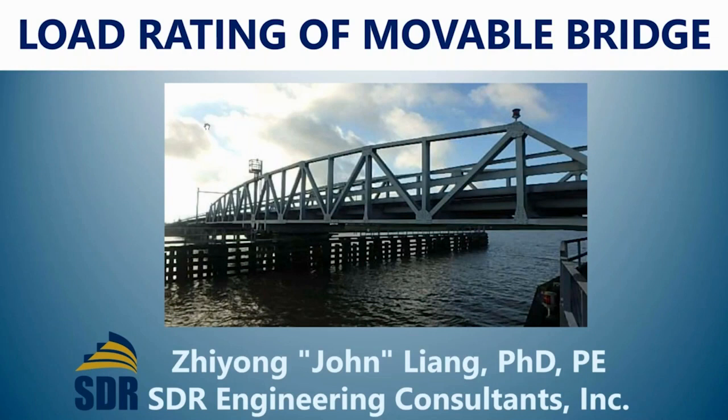So it's very important for us to load rate those bridges because the code has changed, condition has changed. So we have to load rate this to make sure the bridges are safe. But the thing is, for movable bridges, there are always some special considerations that we need to take into consideration, and there are some special tricks to load rate this bridge. Otherwise, if you load rate it like a normal bridge, you almost guarantee that you will make mistakes. So in this presentation, I'll just show how we load rate those bridges using BrR.